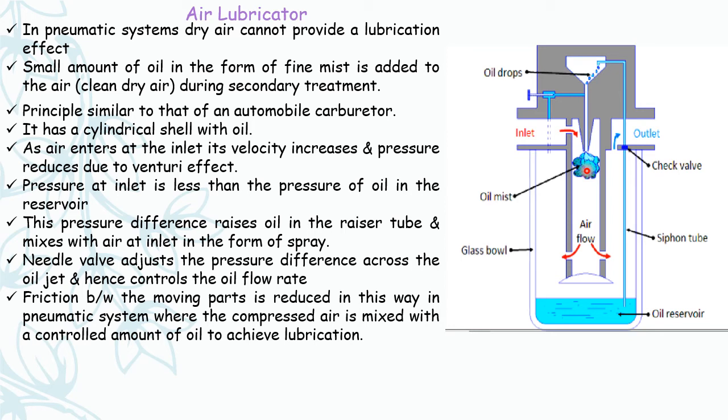You can see that because of the pressure difference between the inlet and the oil present in the reservoir, oil will rise in the capillary tube here and, in the form of spray, that is oil mist, will be added to the clean air. There is a needle valve present over here.